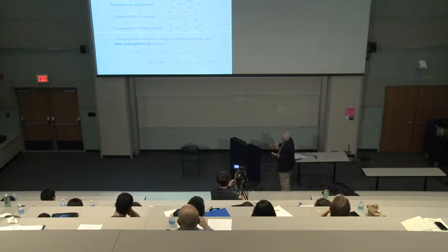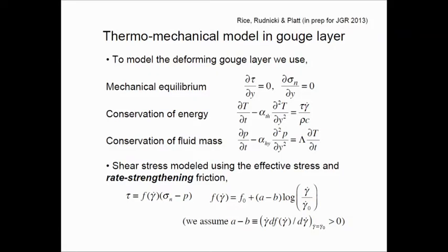There are other things that enter a proper energy equation, but you can look backwards at solutions you get and see that they make small contributions. As the fluid within that zone heats up, it wants to get out of there. There's a flow out, but the advective transport of heat in that flow is rather small, so we don't bother with it. There's also an equation for conservation of fluid mass.